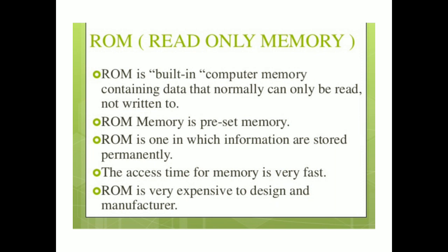It is used to store initializing programs of a computer, microcodes of a CISC processor, supervisory programs of a microprocessor kit, fixed programs in microcontrollers, etc. Its contents are written at the time of its IC fabrication.